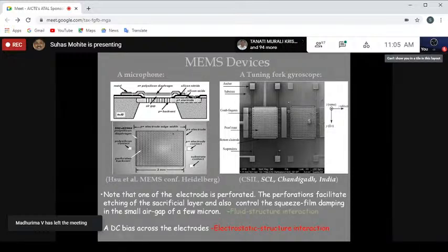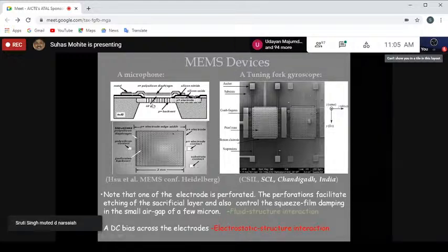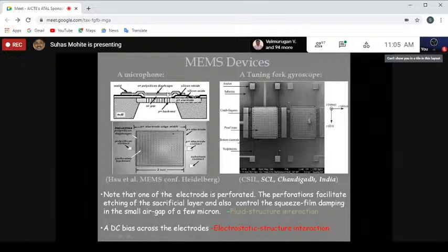So, just jokingly, I would say that my research topic was confined to this small gap and these perforations that you see underneath. So this was the space of a few hundred micrometers. That was the area of research for myself, where I did my squeeze film analysis, where I solved Navier-Stokes equations, and where I developed some closed form formulae for the air and the structural interaction and the behavior of air in a small gap between these oscillating MEMS structures.